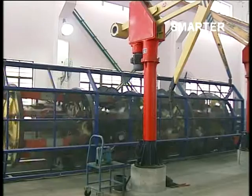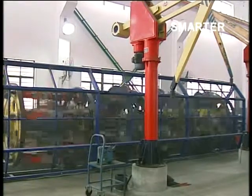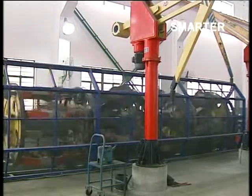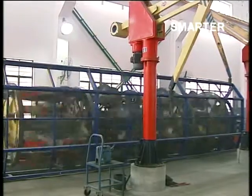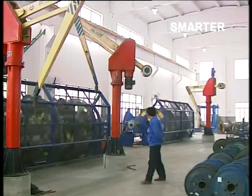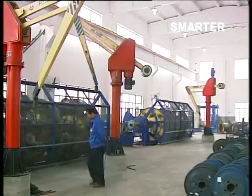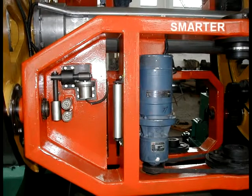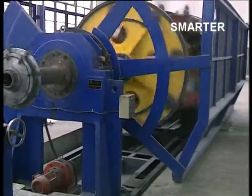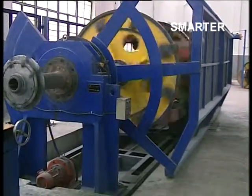The circumference of the 8+16 cage is distributed into 4 equal parts, while the circumference of the 6+12 is distributed into 6 equal parts. The payoff in the cradle is active and driven by an imported DC motor with a sensor for feedback, and with an electric closed-loop control system to keep constant tension from full bobbin to empty.